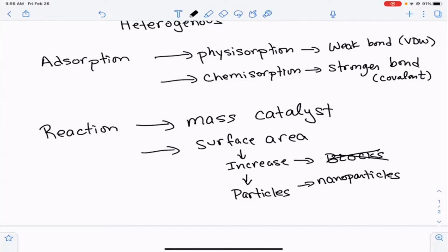But the other problem with nanoparticles is aging, is that all catalysts undergo aging processes where there's things like catalyst agglomeration and that kind of stuff that can happen. And think about most of the reactions that we've discussed in our class and that you've discussed until now in your career, that they're happening at hundreds of degrees C, even up to 800, 900, 1,000 degrees C. And there's just a lot of energy for surface movement of atoms and that sort of stuff in chemical reactors at high temperatures, and nanoparticles just don't hold up very well under those conditions generally.